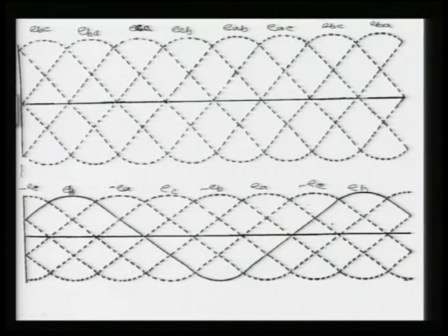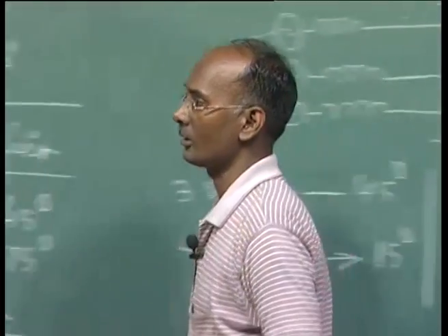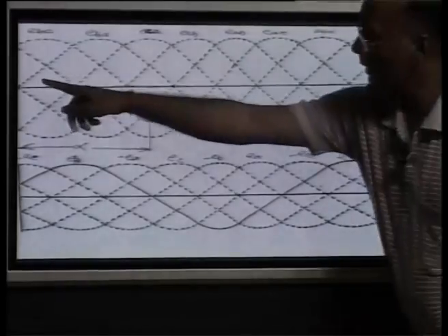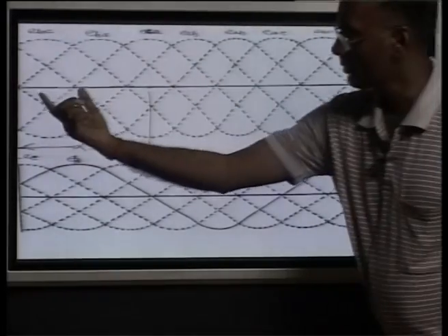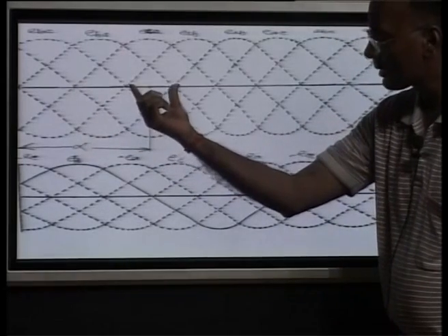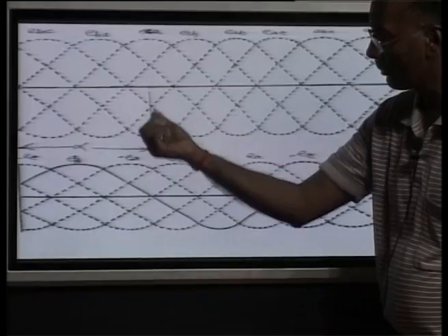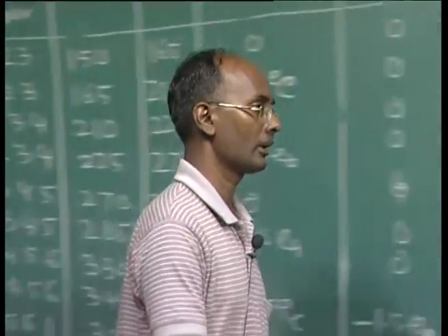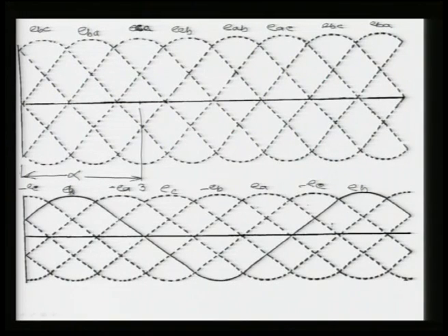We are starting from here, again angle here, and we are going up to 150 degree, alpha is delayed. You see this is your 150 somewhere here, just see here, this is your alpha. Because we are having this 60 degree, this complete EBA is the commutation voltage of valve 3, this is 60, this is 60, 120, and this is the 60, then 180, half of this is 30, so 150 degree. So valve 3 is given the gate pulse here, and then it will conduct, because the voltage across the outgoing valve will be positive. So we are giving here valve 3 voltage.